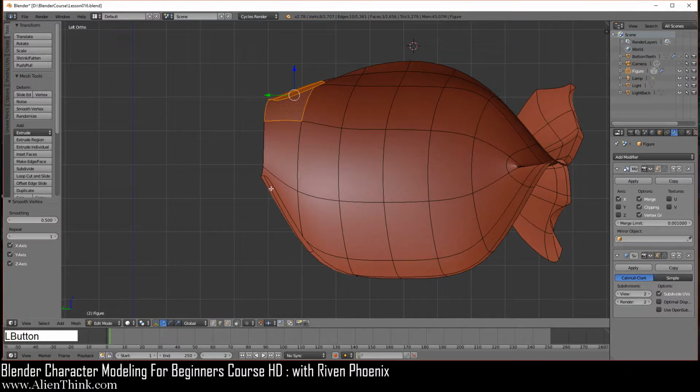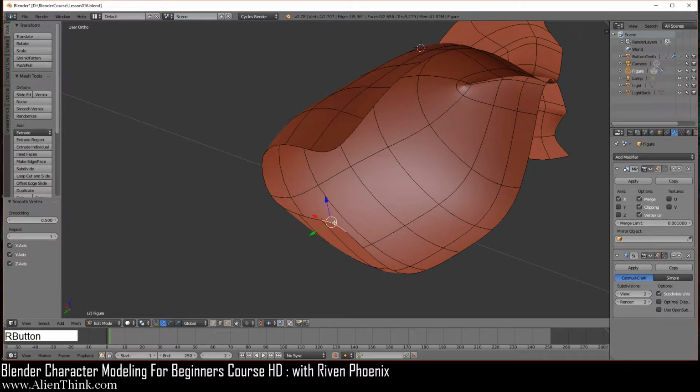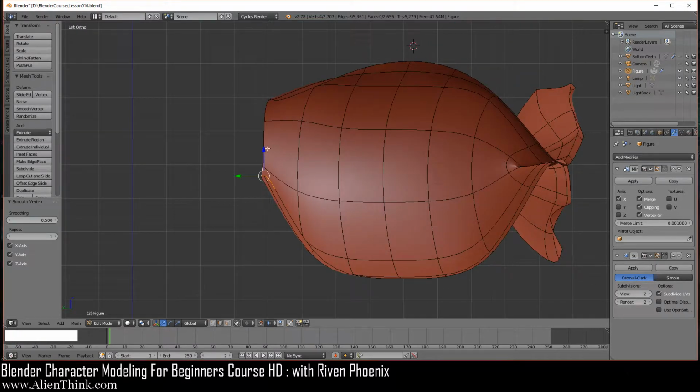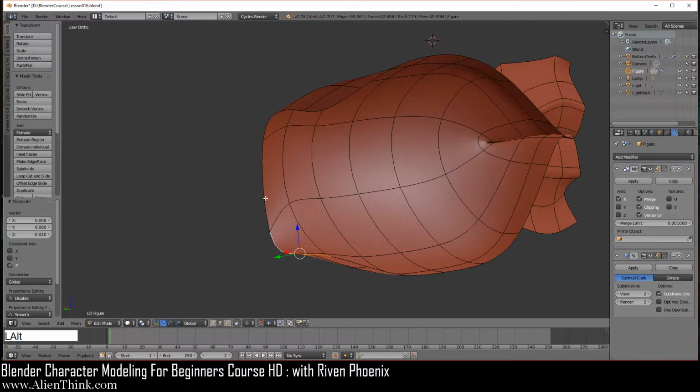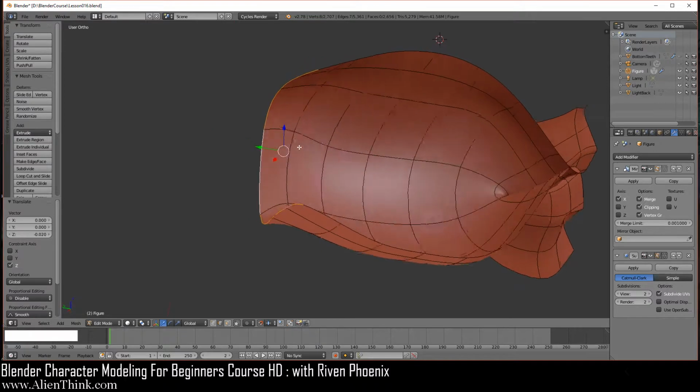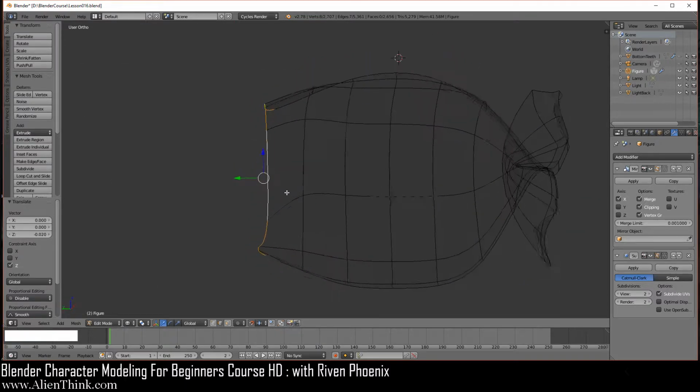Click on the edge select mode, rotate, click on this edge, shift key down this one and this one, Control 3. We're going to click on the blue arrow and bring it down 1 and then 2. Okay, now we're going to do Alt and just click on this edge. So we're selecting. I'm going to press the Z key to show you. This is what I've selected.